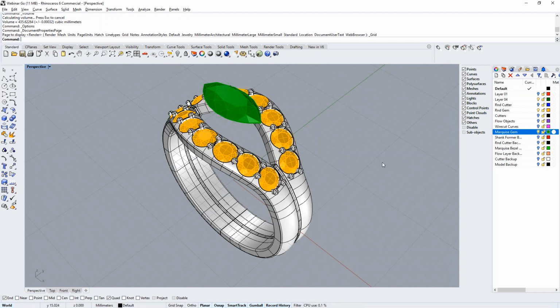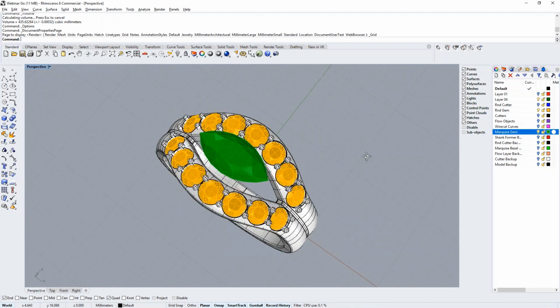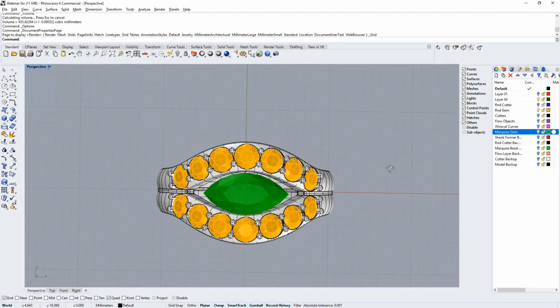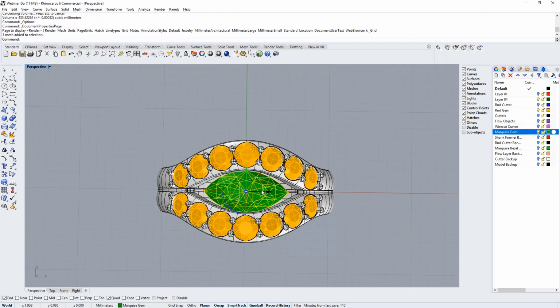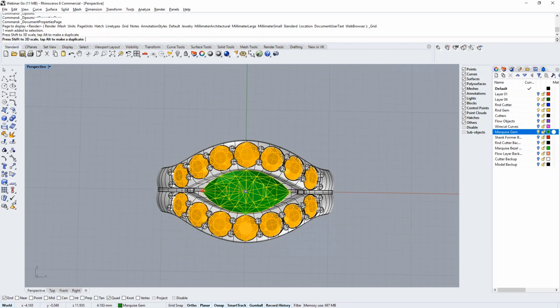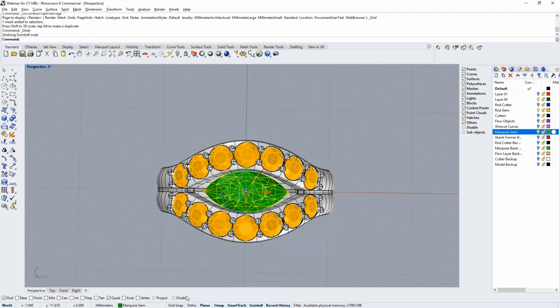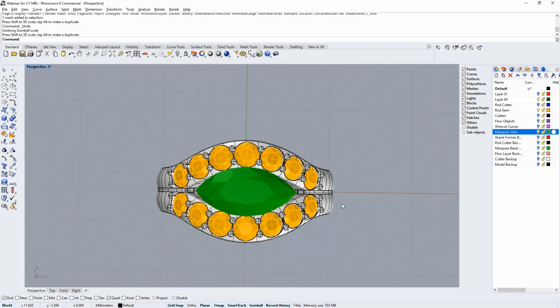And I think in technical support here, where we see problems is where someone will just take the absolute tolerance and just type in 5 more zeros, and they don't realize that that is now the tolerance that Rhino is going to be using anytime a surface is trimmed, or any Boolean union or Boolean difference, and all of a sudden now nothing works.